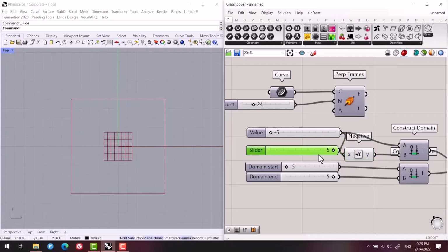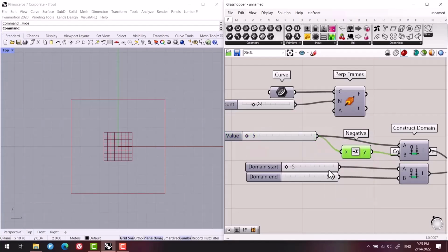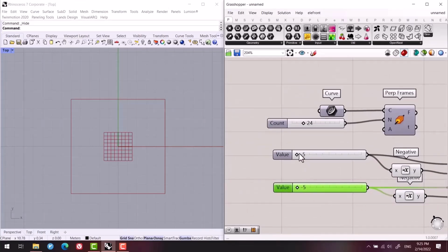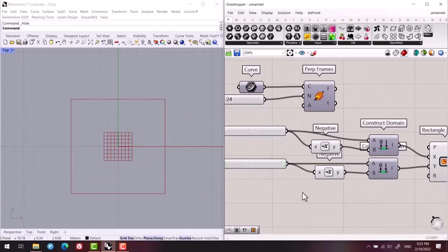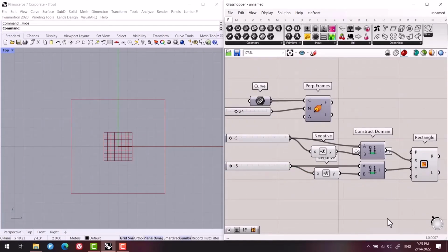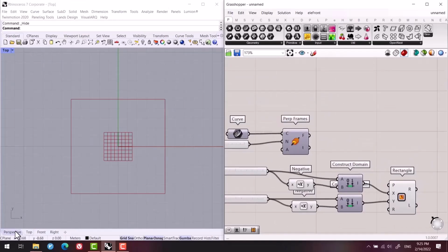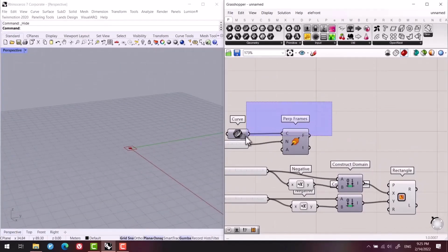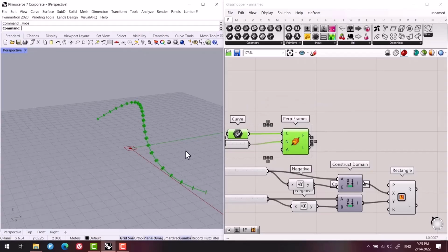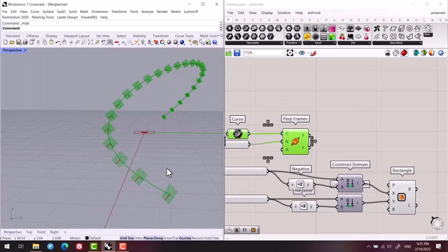And then we have the rectangle at the specified length for the segments. And if we use negative for each of these segments, then we can have the rectangle scaled equally at both sides. Check it out, we can use negative. And then even by moving these 2 number sliders instead of controlling 4 number sliders, we can scale the rectangle.